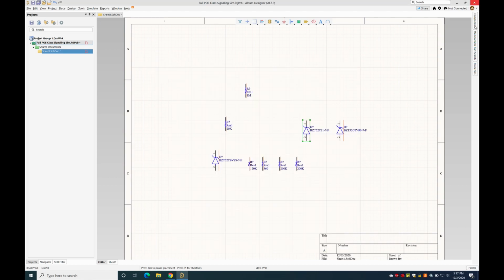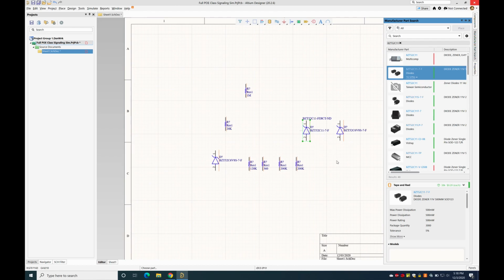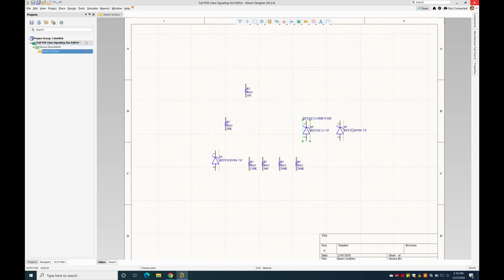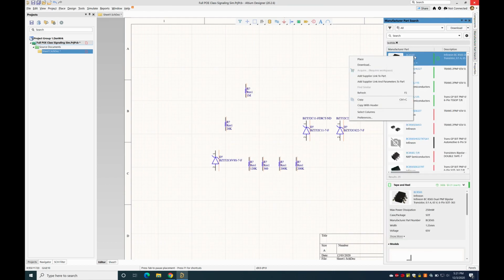Now that we've placed the model compatible version of this component, we'll go back to the manufacturer part search, find the actual component with the right values and everything, and then add manufacturer data and whatnot to this component instead so that everything is just nice and clean and we could fabricate this if we wanted to. Basically, we just use the copy of the component we could find with a footprint and symbol available and then copied manufacturer data to copies of that component for the other 2 values. Q1 luckily also has models available in manufacturer part search, so we'll just use those as well.